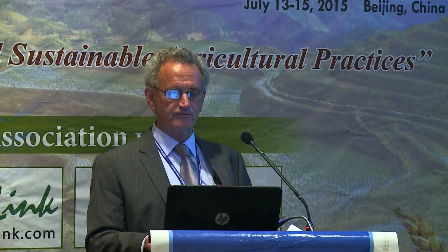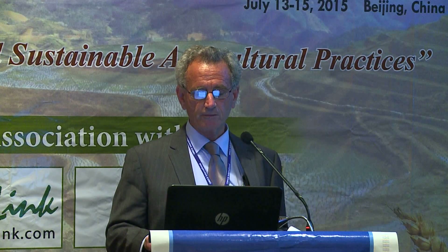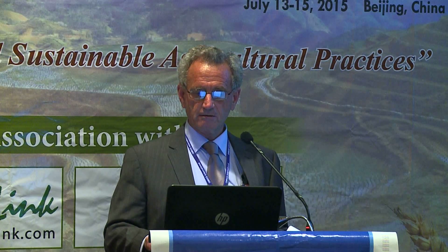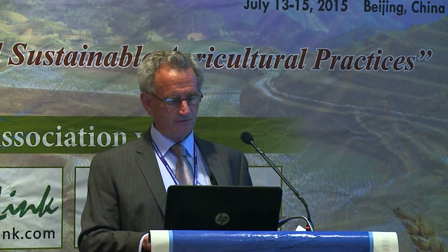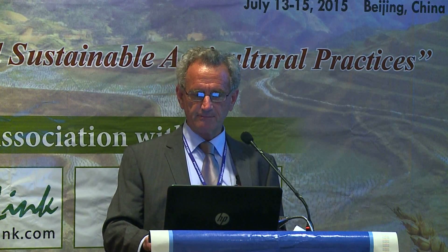For conventional gravity feed systems in developing countries, which of course use gravity feed because it's all that can be afforded, a minimum head of water is recommended, usually greater than 1 metre. With measured irrigation, it is far more energy efficient because the head of water required is much lower. And finally, emphasising that evaporative measured irrigation is an example of a low-cost, simple technology with a high level of control over the application rate to each plant.